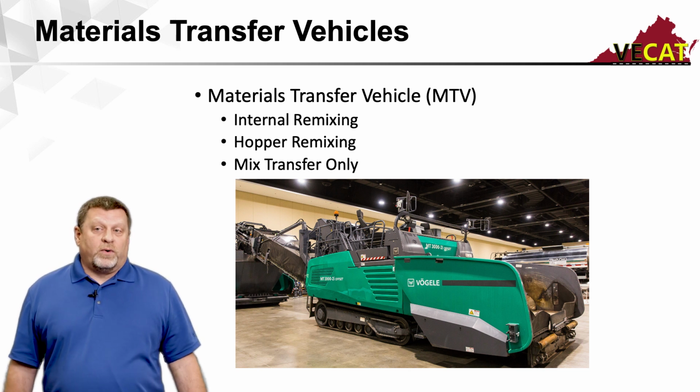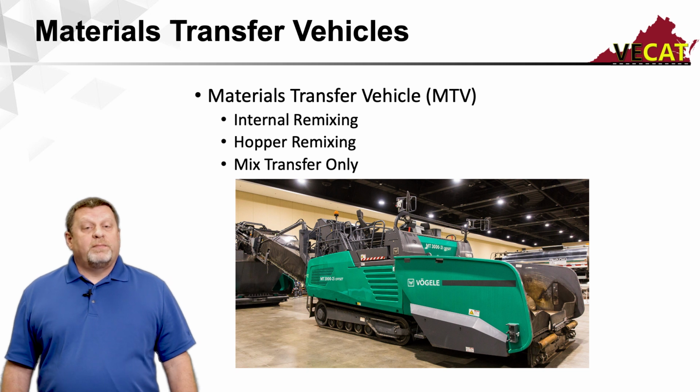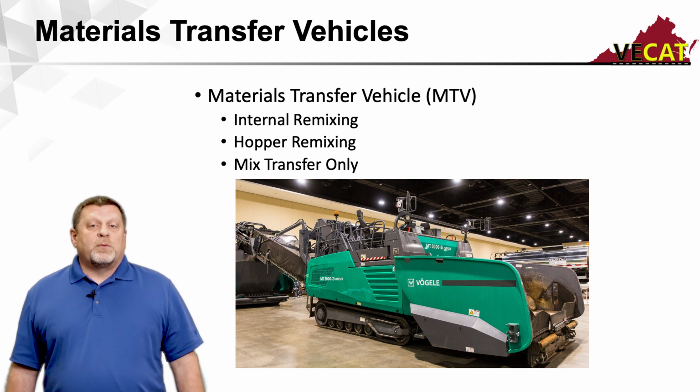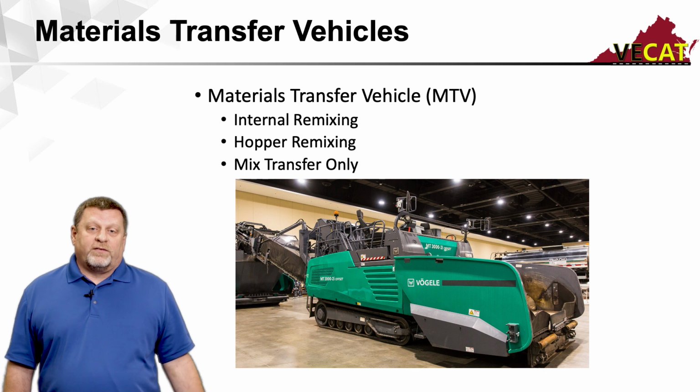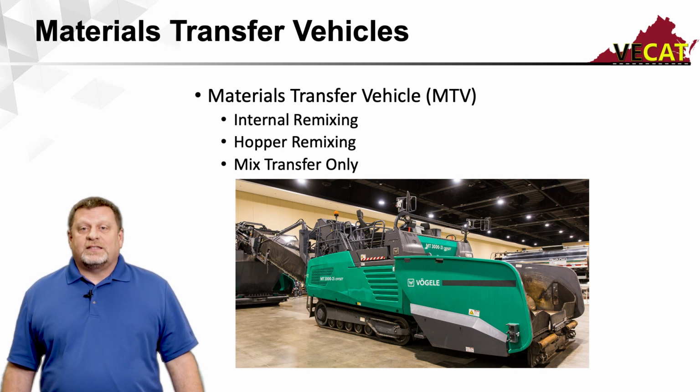Some of them have internal remixing, some of them have remixing inside the hopper, and some of them will actually only transfer the mix from the load that's being deposited into this materials transfer vehicle into the paver hopper. The advantage of these MTVs is it doesn't have any contact with the paver itself, so that it prevents any bumps or anything that can impact the final ride of your pavement.